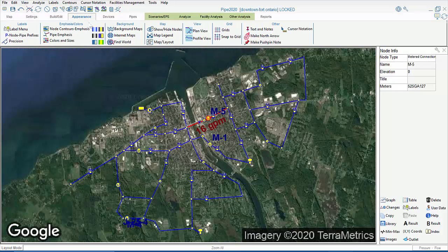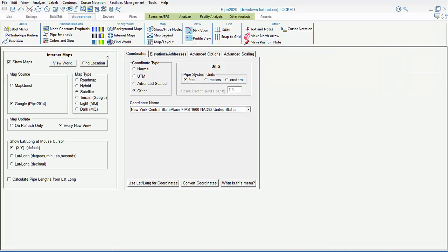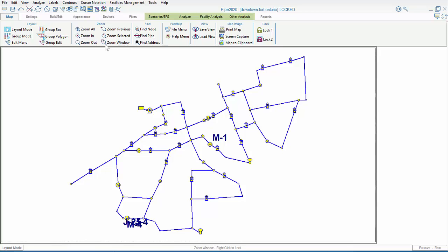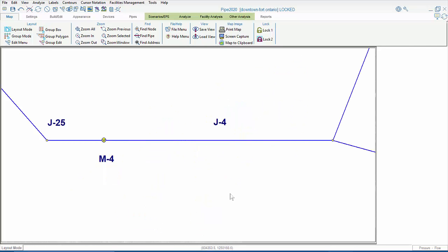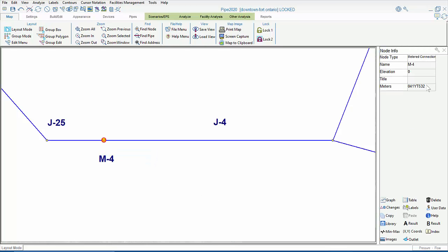However, unlike residential meters, we account for the position of the metered connection node within the pipe, and the model weights the flow to either end of the pipe based on the node's differential location. In other words, for a metered connection node which is 30% of the distance along the pipeline, 70% of its demands will be distributed to the closest node, and 30% to the farthest node.